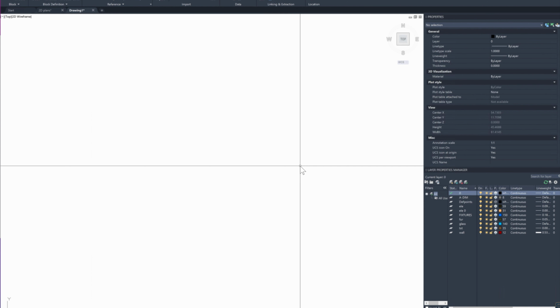Now, blocks normally are when you tell AutoCAD that you have a set of objects or lines that, even though they're not touching each other, I still want you to treat them as a single object. These are sort of saved like a sub file inside your file, and so they are formed together, and you can edit them after you introduce them and set them up, and start using them and inserting them into your drawing as many times as you want without having to copy or redraw the same object over and over.